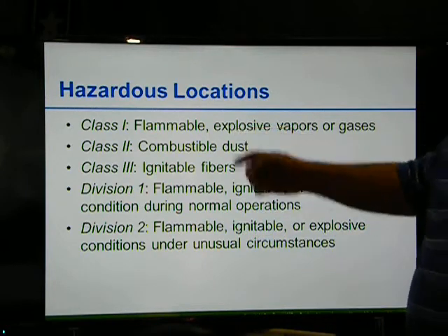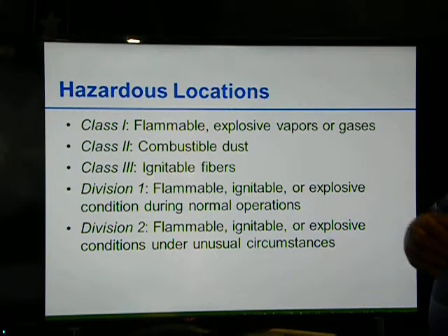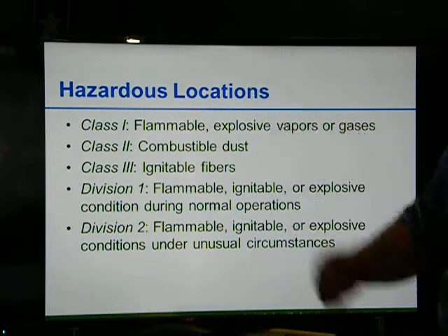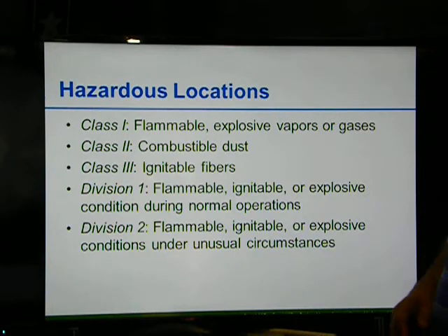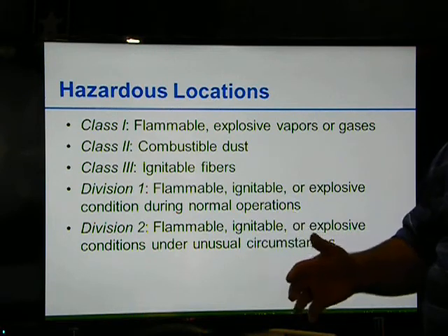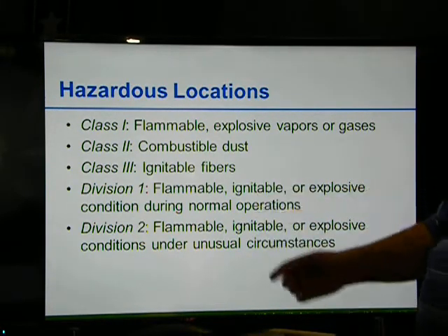Okay, so Division 1 would be present at all normal operations. From the time that somebody punches in, say you only have one shift, 7 to 5, or whatever it may be. It's only open from 7 to 5. Well, that's your normal operation. Somebody's there. So that's a Division 1.